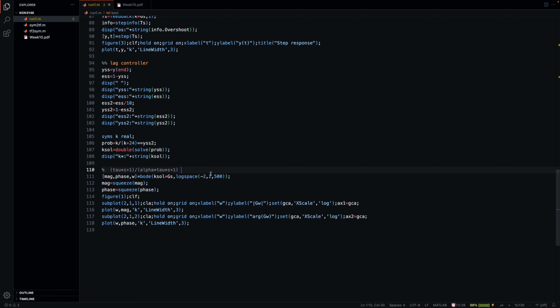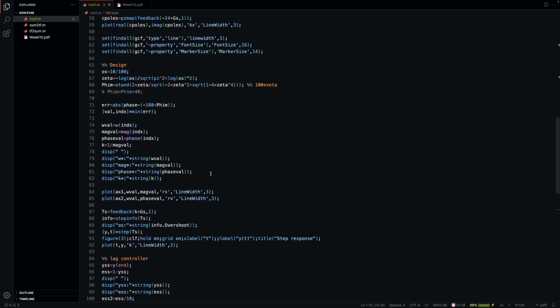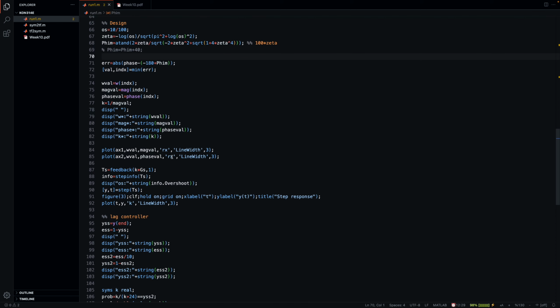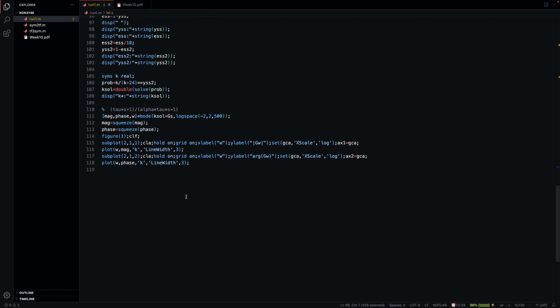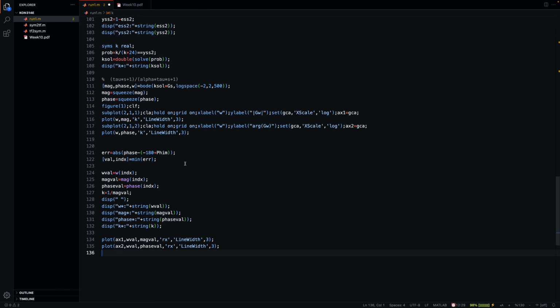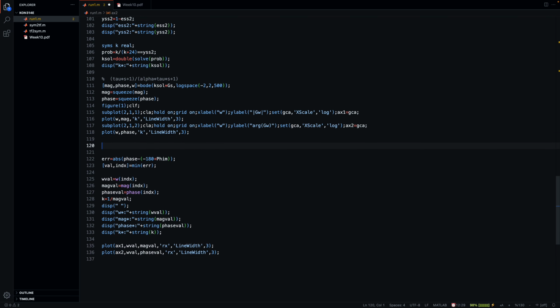So again, we are going to look for the phase here. I'm just going to use the same old stuff that is given here. Let's take this up to this point. But there is a slight problem now, because now we have this times Gs, and this should not be equal to -1 and 180 degrees, or in our case, since we're looking for a certain overshoot, minus 180 degrees plus phi m. Now if I plug in j omega, we will have j omega here and also here.